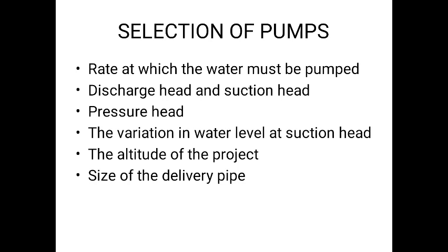Selection of the pumps. First, the rate at which the water must be pumped. Second point is discharge head and suction head. Third point, pressure head. Fourth point, the variation in the water level at the suction head. Fifth, the altitude of the project. Sixth, size of the delivery pipe.